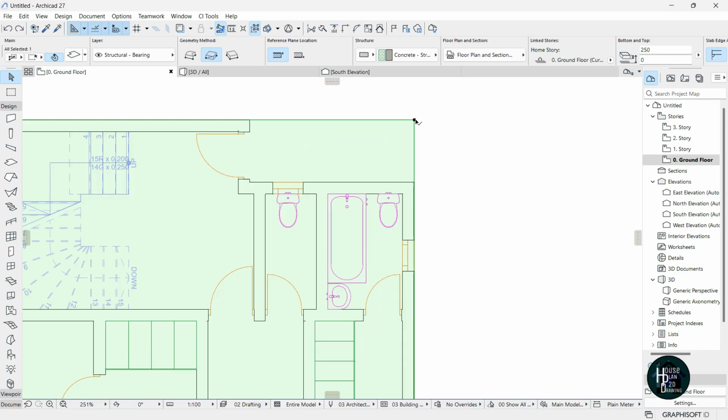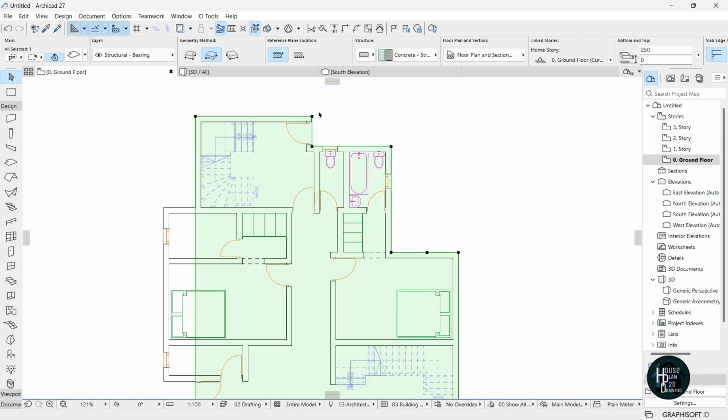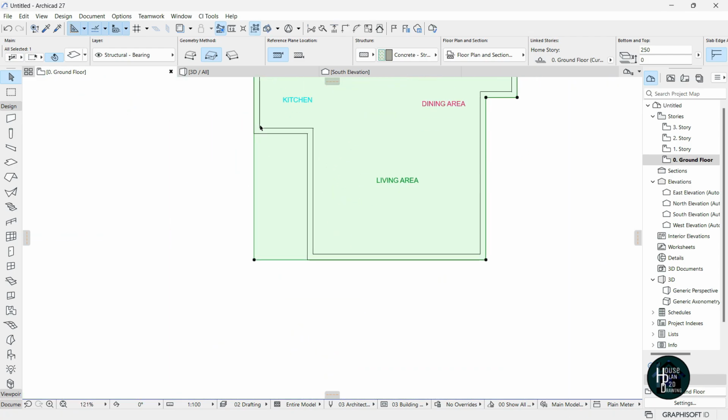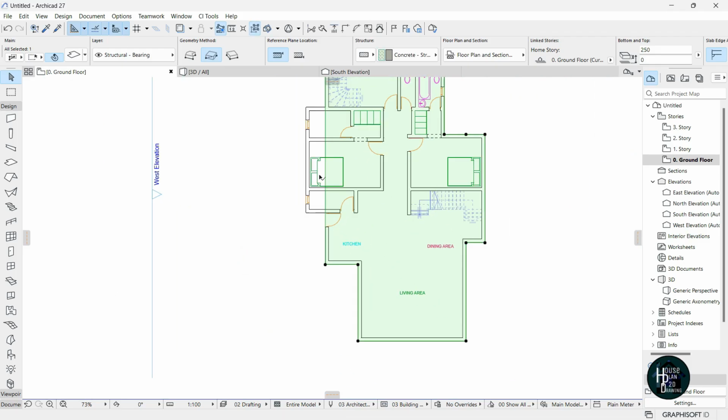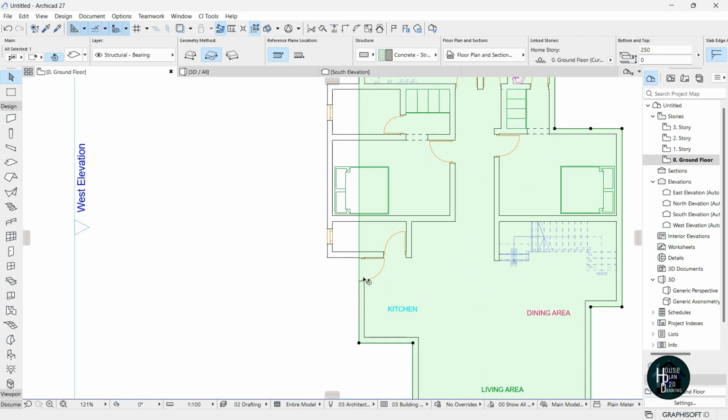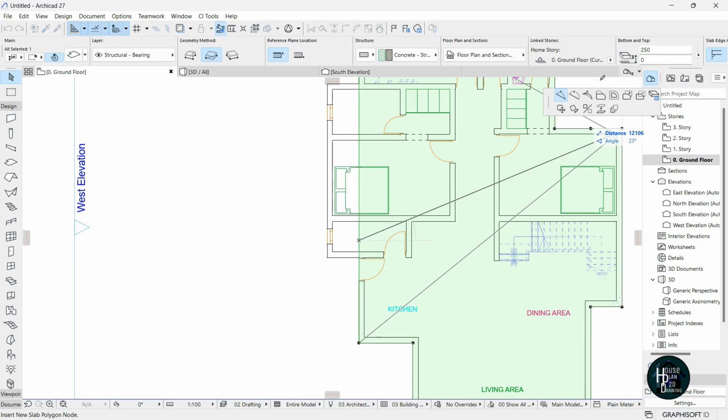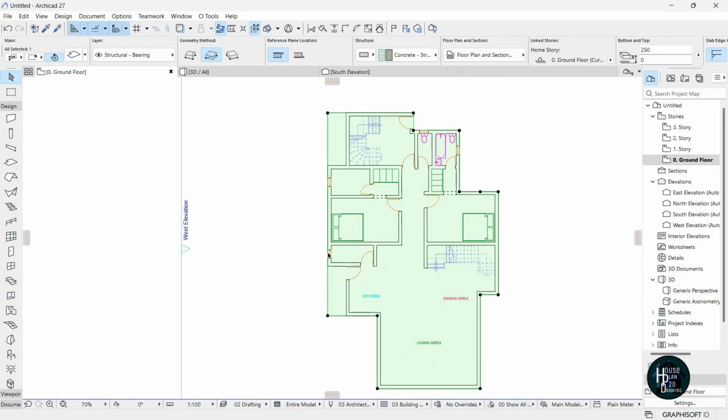Click this node. Select this subtract from polygon, click this, straight to this side and click. So it's going to cut out that side away. And for this other side, you want to do the same thing. Click this and click. All right, now for this other side that is being opened, you just want to click this edge here and select this offset edge so you can move this edge to meet this side, then click. All right, you want something like this.